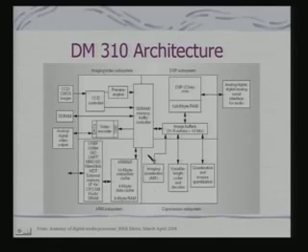The basic difference is that OMAP is targeted for communication as well as this kind of media processing applications. This one is more targeted towards media processing. So you actually have CCD controller kind of blocks incorporated into the SOC and coprocessors for each and every task related to media processing. And we can see now how a complete embedded system can be built around it.